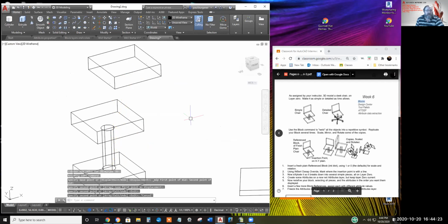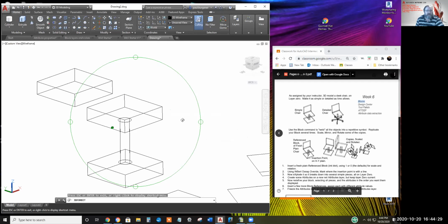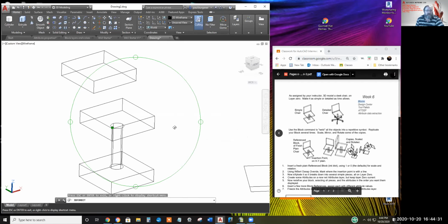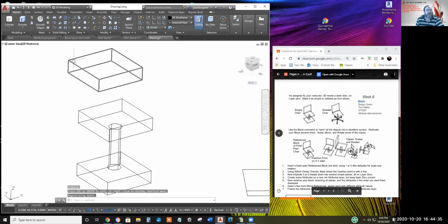And I'll place another copy that's somewhere out in space. Get the warm and fuzzy. You can see, yup, it's far away from where your intuition says you put it. That's okay. I'll use the align command to set it somewhere. Again, I prefer the old 2D align.